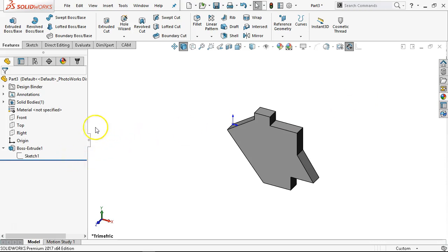It kind of forces you to think about, yes, I am editing the sketch. I'm making these changes. It's not just there in front of you. And if this is going over to the assembly, starting a habit of leaving the sketch open and then finding that you go into the assembly and, wow, where's my part? I've got this error because the rest of my geometry is not rebuilding correctly because one sketch was left open.